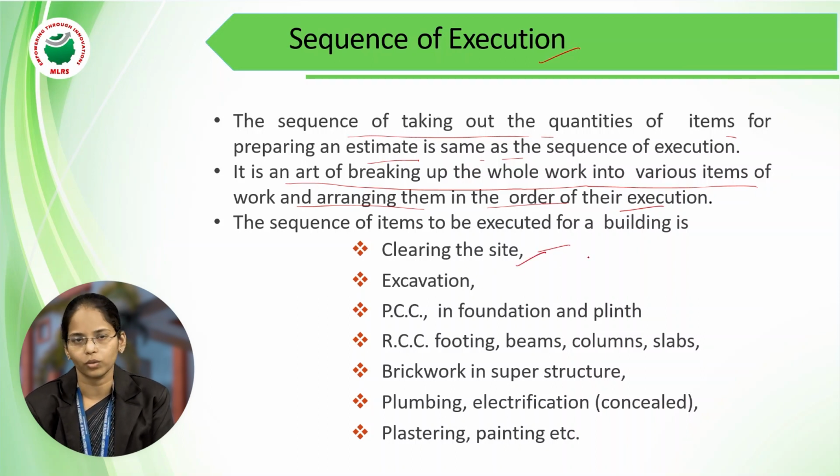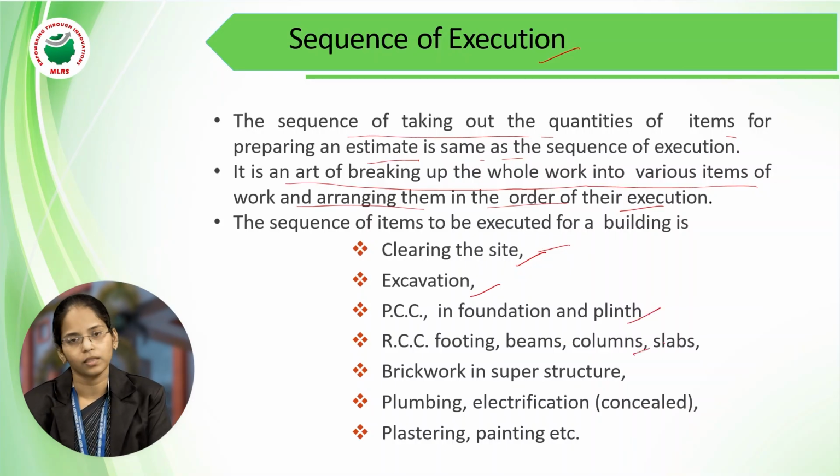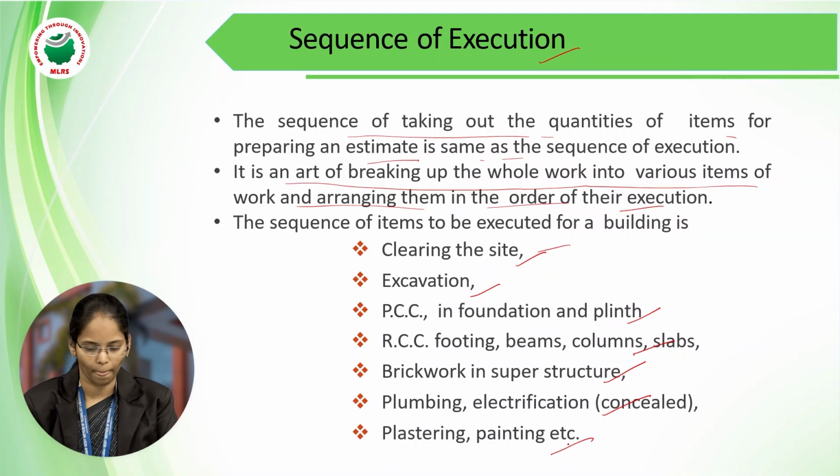Clearing the site. First, we need to clear the site, and then excavation, PCC in foundation and plinth, RCC in footings, beams, columns. Next, brickwork in superstructure, plumbing, electrification. These are also most important things. And next, plastering and painting, etc.